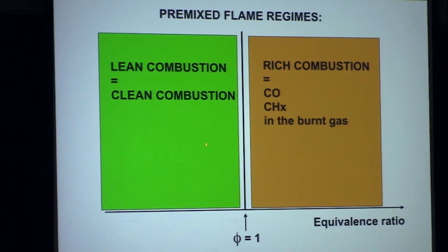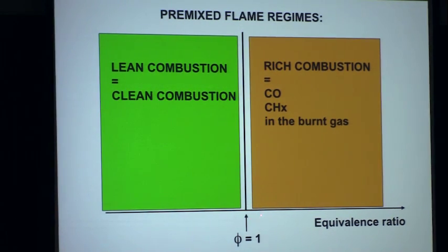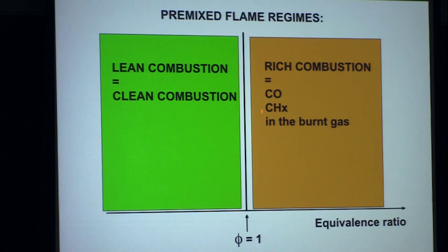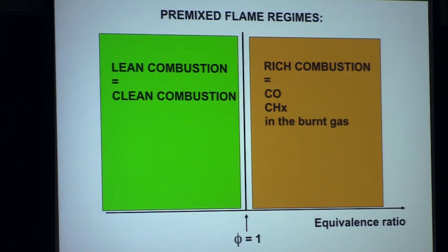So if you go to industry, in practice quite often, there's a number here, the stoichiometric ratio, 1, which splits the world in two. On this side, you get the lean flames, and those lean flames are good because you don't put a lot of fuel there, so the pollution levels are better. If you put too much fuel, then you get a rich combustion, you start producing CO. CO, 0.4% is sufficient to kill you. Okay? It's not like CO2. CO just kills you much faster.